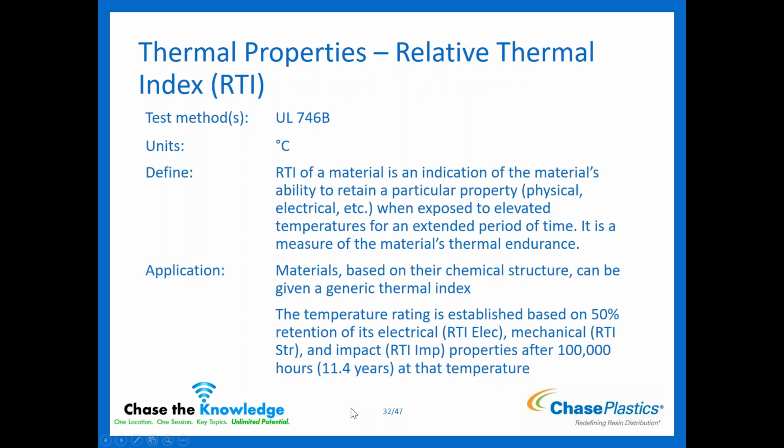Relative thermal index, RTI. This one's a little different because this is done through UL, but something you're definitely going to see on your materials data sheets if they have this rating. RTI is an indication of a material's ability to retain a particular property. If you're looking at the RTIs, it's either physical, mechanical, electrical, or impact that are the standard ones, when exposed to an elevated temperature for an extended period of time. Essentially, this is a measure of the material's thermal endurance.